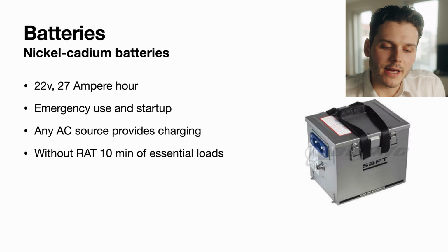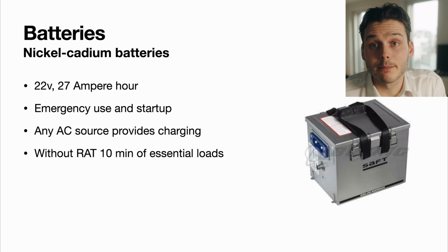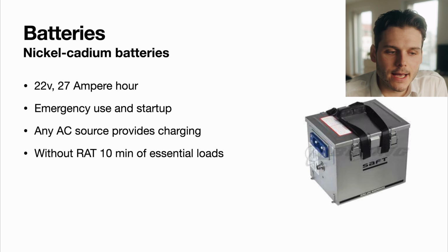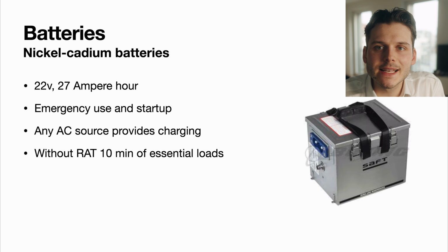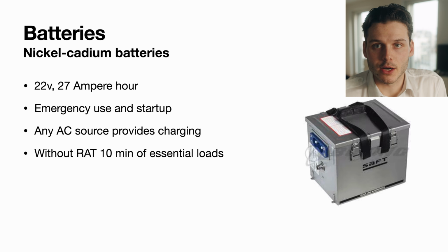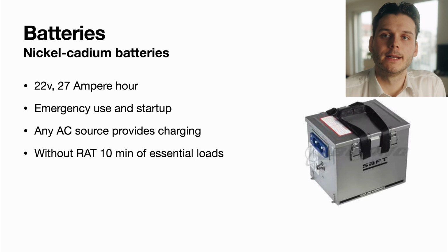Also, if we have a ground power failure, we do leave the aircraft switched on, because in our company there's actually the rule to have an aircraft switched on in case a different crew will take up the aircraft within less than 3 hours. So if we go on block at like 1 in the afternoon and another crew will come like 2 hours later, we'll have the aircraft switched on with the power on parking.